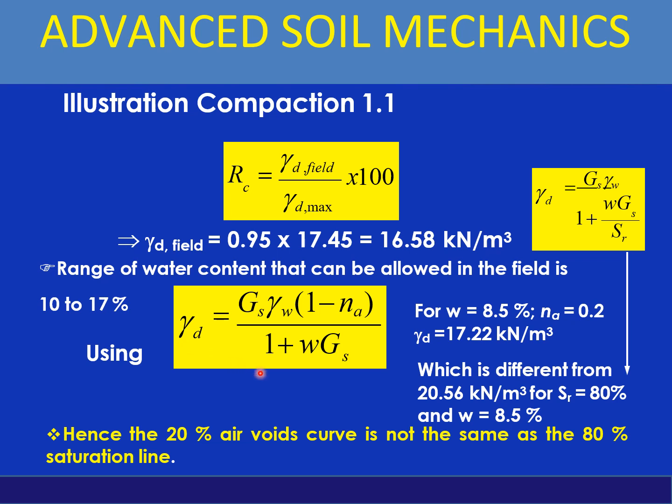Okay, if you just look at this relationship, this is used to draw the saturation line. And this one is to be used for the air void curve.